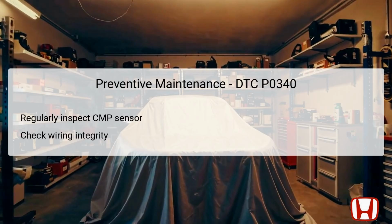Additionally, the wiring and connectors leading to the sensor should be inspected for wear, corrosion, or damage to ensure robust signal transmission. It's also beneficial to establish a schedule for routine diagnostics, as periodic checks can help identify potential problems before they manifest as DTCs. Adopting these preventive measures can contribute significantly to the longevity and reliability of the engine system.